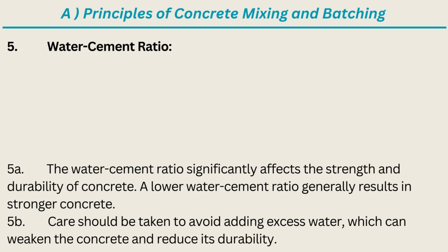5. Water-cement ratio. 5a. The water-cement ratio significantly affects the strength and durability of concrete. A lower water-cement ratio generally results in stronger concrete. 5b. Care should be taken to avoid adding excess water, which can weaken the concrete and reduce its durability.